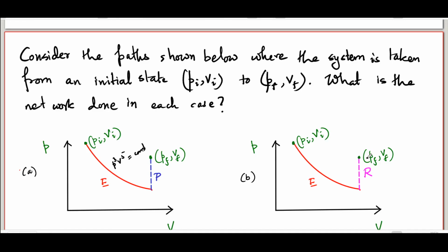Note that in this case both the vertical lines have been drawn as dashed lines because here the initial state is in equilibrium. If I draw the thing sufficiently slowly, at the end when the volume reaches Vf, the system is in equilibrium, and the final state once it reaches PFVF, everything can settle down. This of course occurs not as the propeller is turning, but once the propeller has been switched off, after a while the system reaches this steady state of PFVF.